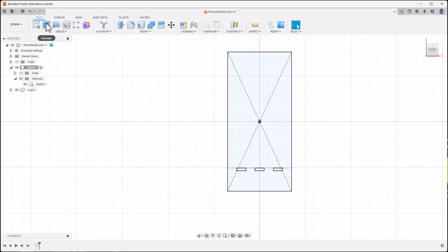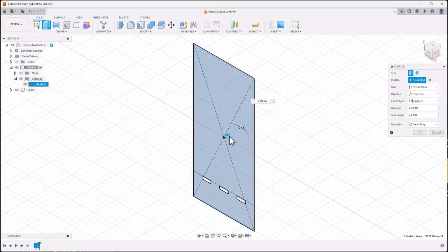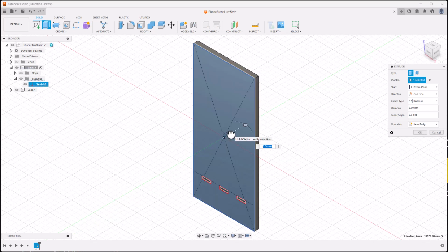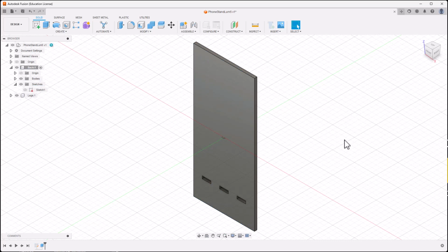Now I am going to extrude it. So I'm going to extrude, and then again, notice it didn't turn for me, so I'm going to go like an orthogonal projection or an orthogonal view by clicking my little home here. So I'm going to extrude this backwards or forwards. But this is another one of those key dimensions, and not 5, not 3, but I can actually extrude this thickness. So I type in T, click on it, give it a second to think, and then there we go.